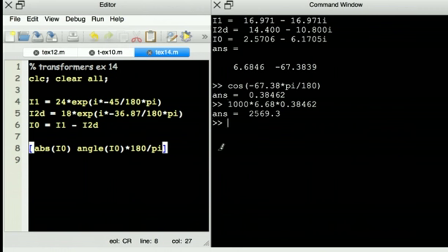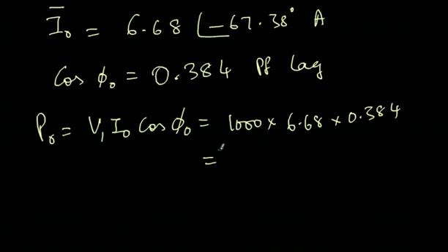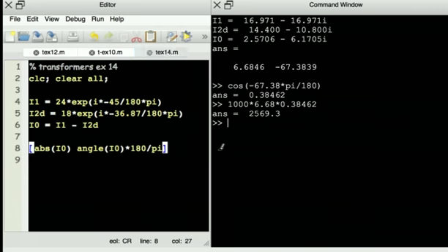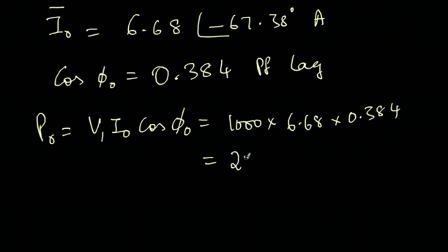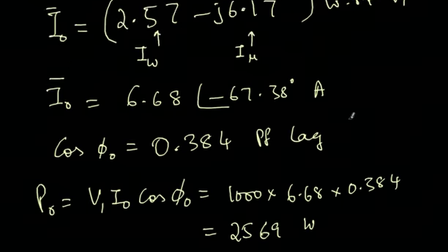I'm sorry, is it? Yeah, that's correct. So 2569. So this is watts, 2.569 kilowatts. So this is the no load power of the transformer.